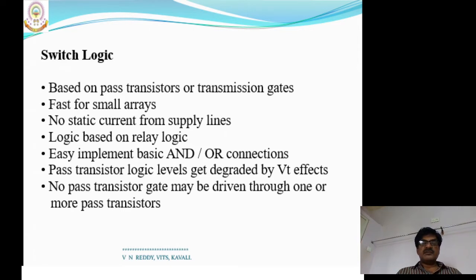The advantage of realizing using either pass transistors or a transmission gate is, especially with the pass transistors, the less number of transistors you can realize. No static current between the power supply rails, and you can easily implement AND and OR gates.